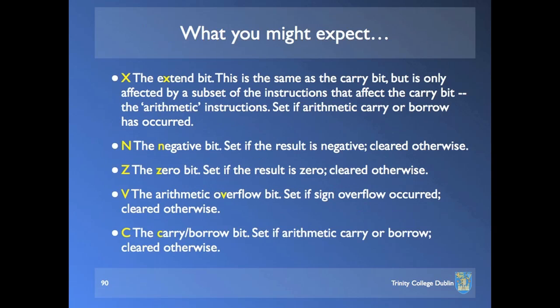You'll have to explicitly use instructions that set either the condition code register or maybe one of many condition code registers in some RISC machines. But anyway, in the 68000, if you look at your instruction set summary, you'll find that a great number of instructions have an effect on the condition code register bits.